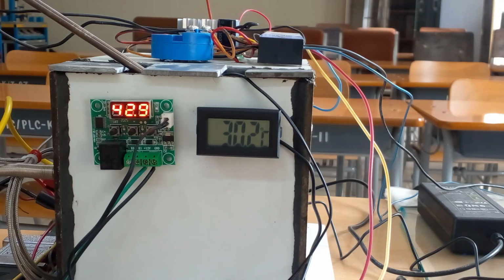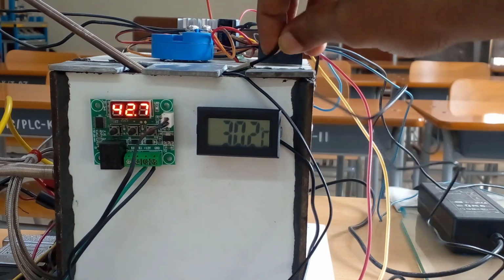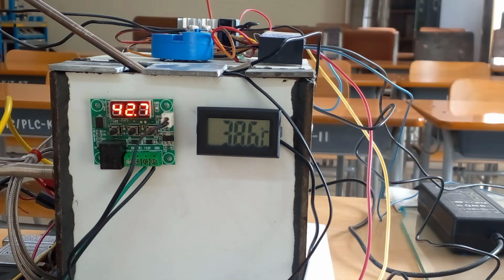The PID control program for air temperature control is functioning properly now. Now put the sensor of the inlet local temperature meter in the outlet path of the heating chamber. Check whether these two temperature meters show the same temperature value for outlet air, as both of these meters have been placed in the outlet path of the heating chamber.